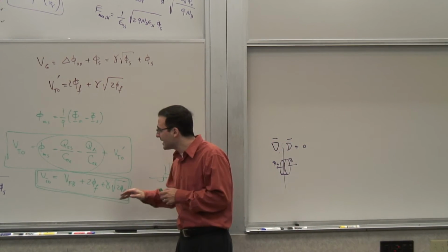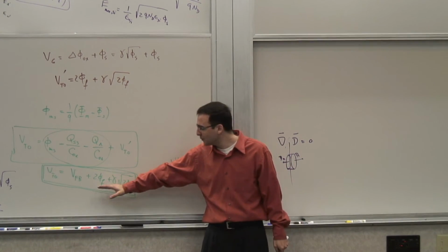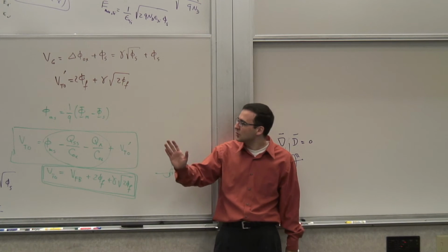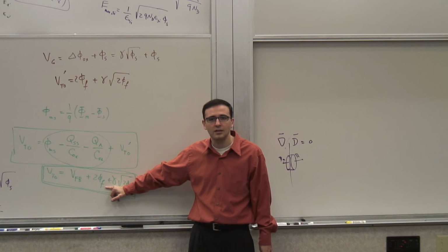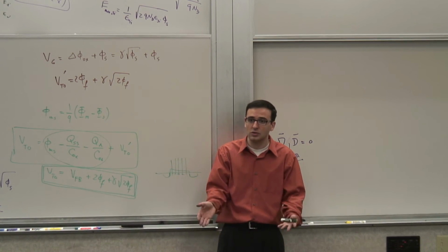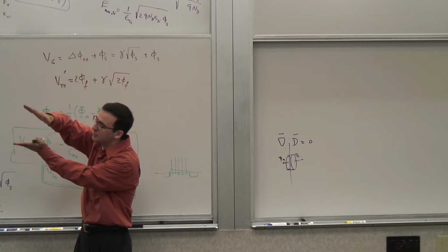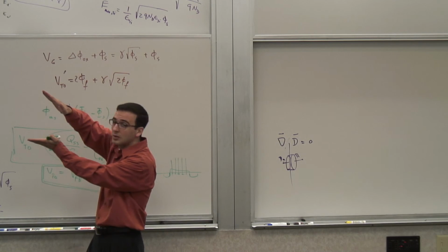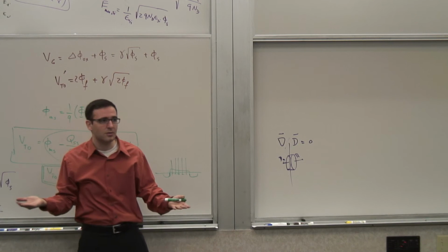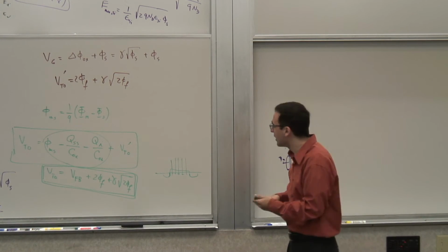I ignore all the inversion charge I've induced at the surface up to this point, because it was not large, it's a weak amount of charge. But anything beyond this point, if I apply some voltage in excess of this voltage, could induce a lot of charge. Because now I am already at phi F, so any change will raise my Ei over EF by a larger amount, and through the exponential I get a much larger number of charges, which is proportional to the applied potential.